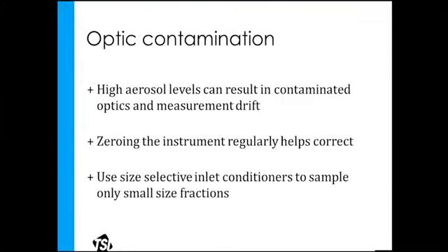And then the DustTrak and some other manufacturers have that sheath air, so it's clean air going in, carrying the dusty, dirty air down the middle of like a clean carrier tube, basically. Another way to address that is, say I'm out at a junkyard or a construction site, concerned about respirable silica. It's really dusty. Well, put an inlet conditioner on and put that PM4 impactor.